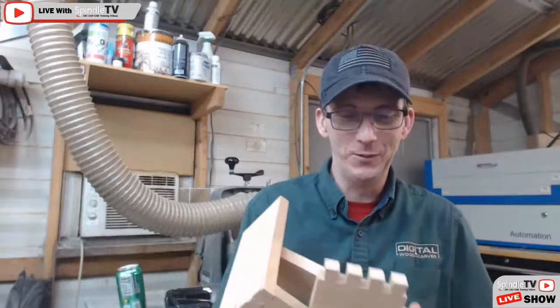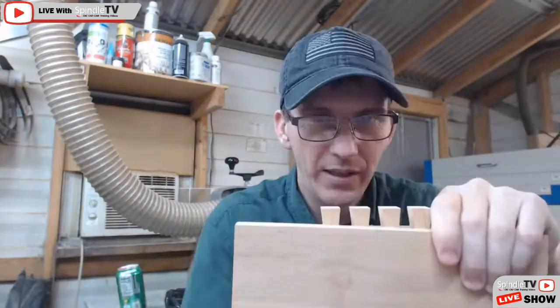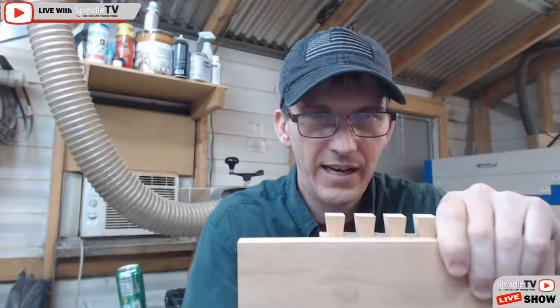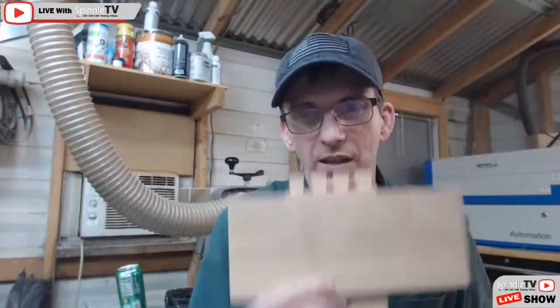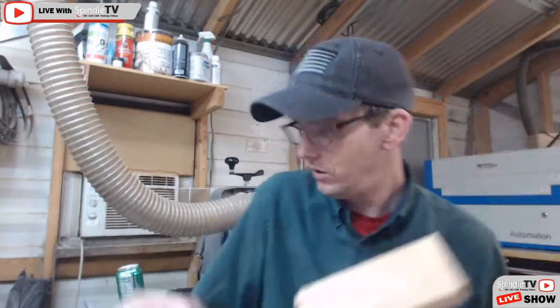If you guys are in a hurry and want to just go through it, but what I would damn sure do, knowing that my cutter's coming from behind forward, I would absolutely clamp a faceplate board on there to help get some stability, so that as it's coming through, it doesn't pull those fibers with it and tear it out. So that's how I would address that. But once this gets glued and squared up and everything, it'll go well together.